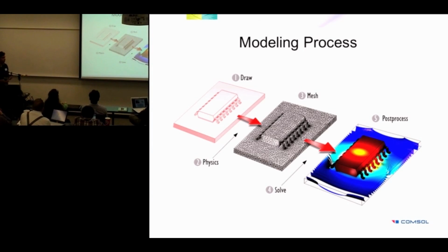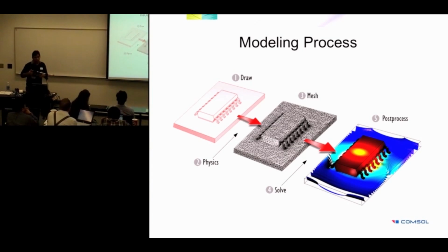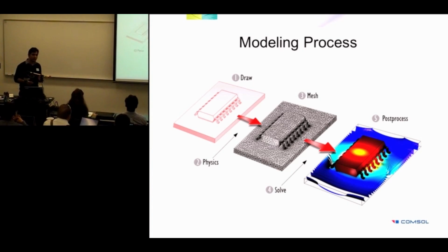So once you are drawing a geometry, there are a few questions which you should ask yourself. What kind of analysis do you want at the end? Can you draw a geometry which is not 3D? Can you assume something there, can you make certain assumptions? And when you are making this geometry, you also have to think that you are going to mesh it and you are also going to solve it. So what kind of computational resources do you have so that you can solve it? You should also ask a few other questions.